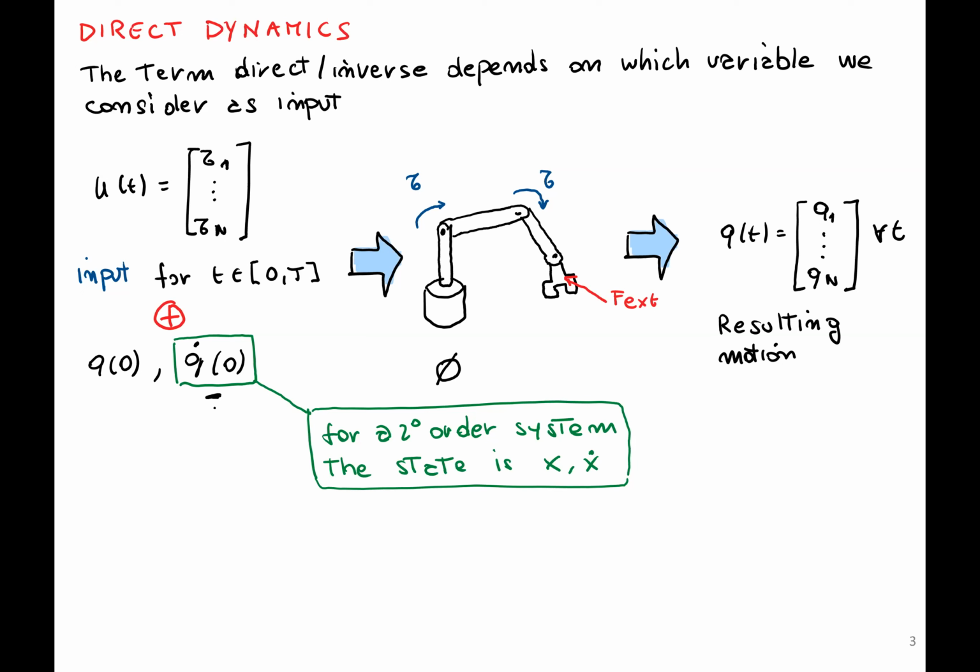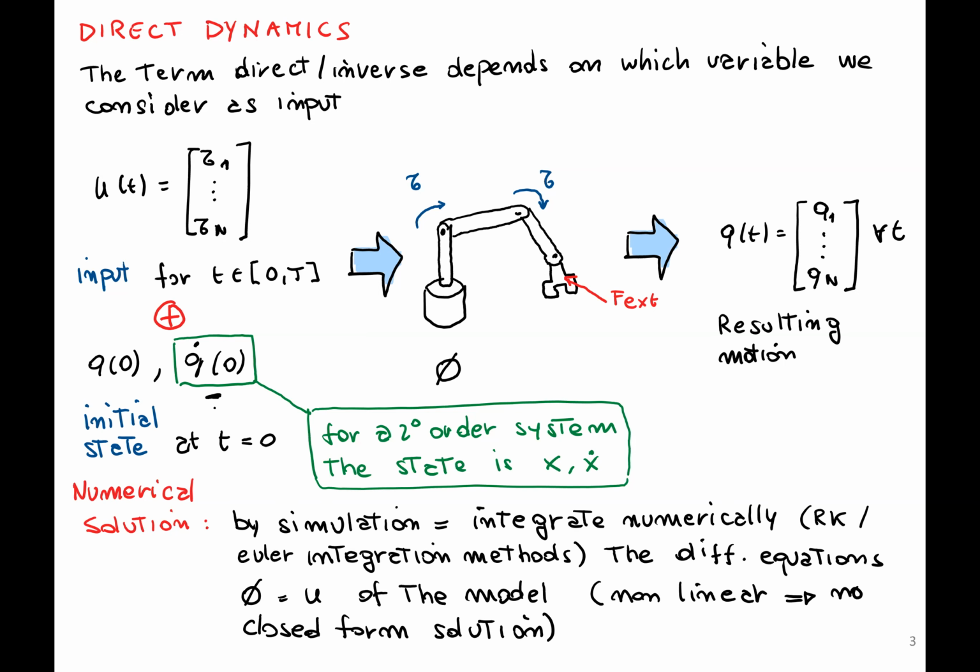And if we don't have a robot, for example, we can use this dynamic model to select the dynamic quantities like the masses of the links and inertia, because we want to predict what will be the acceleration over time given the maximum torque provided by our motor.